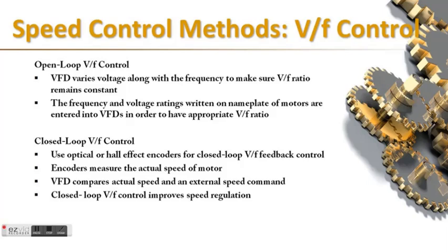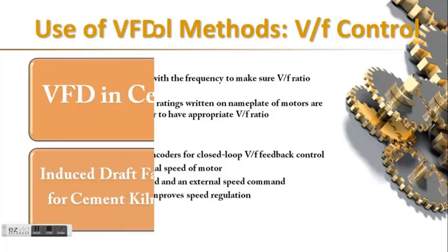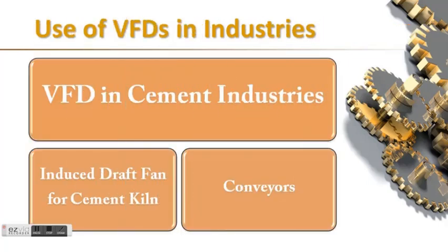Closed-loop V/F control improves speed regulation, however, it is not commonly used as it induces additional cost and complexity of the system.